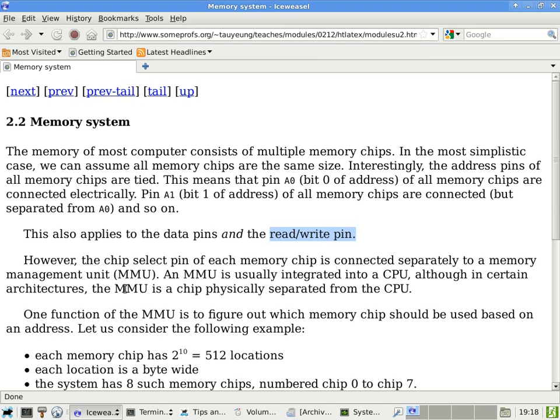Are we doing okay so far? We are stacking up all the memory chips to give us an illusion that we have location 0 all the way up to location 2047, even though each chip only has 512 bytes. So getting back to this example, which chip do you think has our location 600? Chip 1. Okay, the second chip, chip 1. So location 600 is probably somewhere around here.